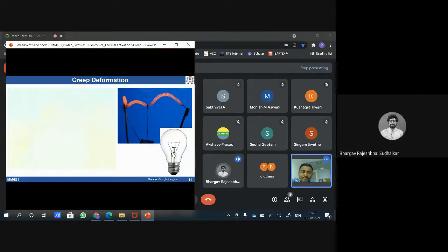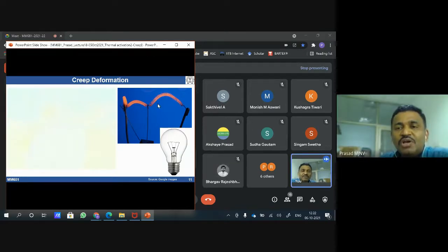So that it doesn't get oxidized. Basically tungsten, moly, high refractory elements with high melting points usually undergo easy oxidation. We know that higher melting points are good for creep resistance, but at the same time these elements, moly and tungsten, will undergo easy oxidation. If it gets oxidized, it becomes powdery.